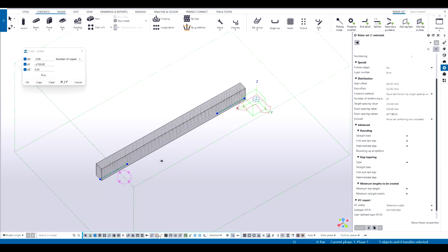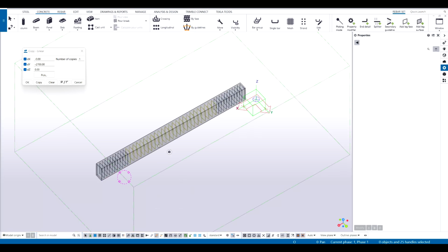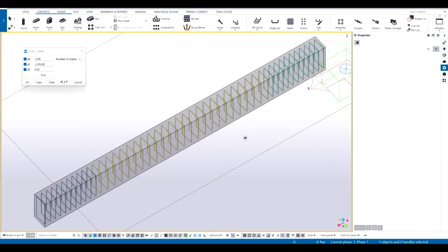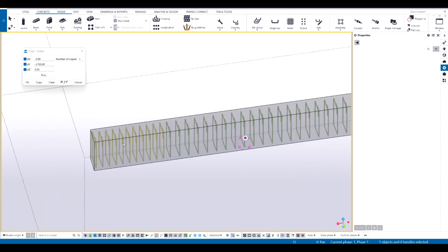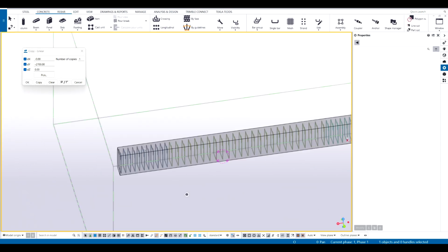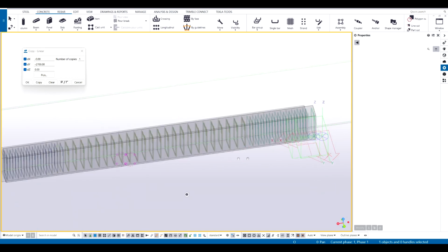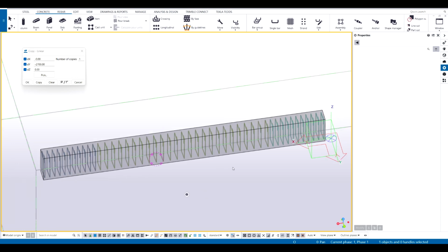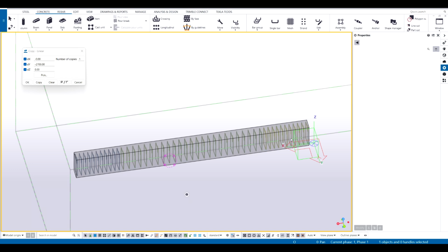But if you click on this button here, select rebar groups, this is how it basically allows you to select groups. Another thing is, let's turn this off and turn on the color group option. Over here, Tekla will tell you that although it has one rebar set, the three of them are three different groups. Maybe the spacing is different or the property is different, but it shows you the division of the rebar groups. So I can turn this off for now. This comes in very handy.